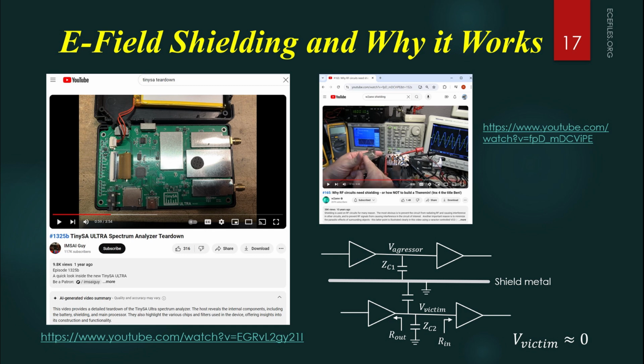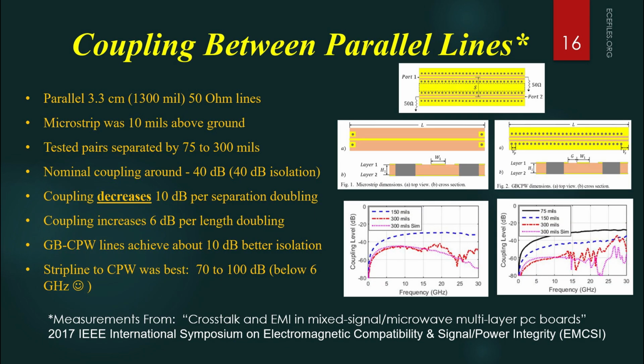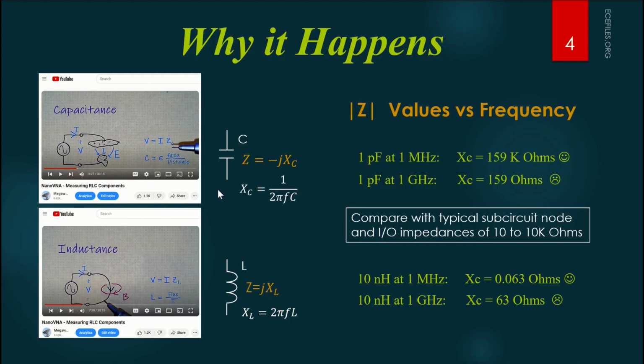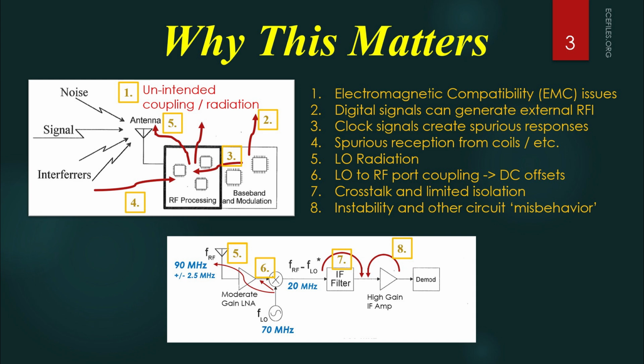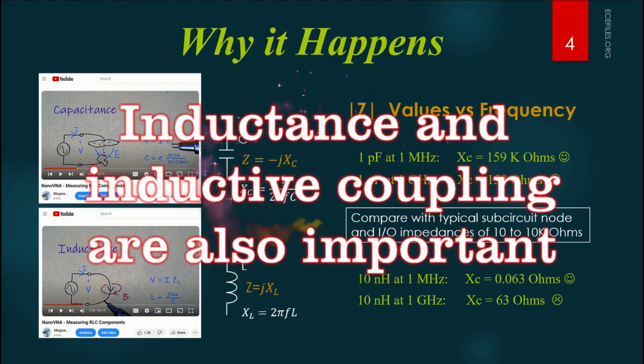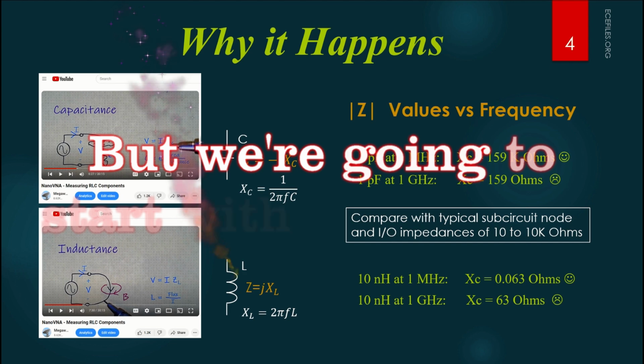And you may have heard of microstrip traces or coplanar waveguide. If you haven't, don't worry. We're going to talk about those and define those and why you need them. We build our circuits with transistors and integrated circuits and inductors and capacitors, but we also end up building things we don't think about, what are called parasitic couplings from one circuit to another. And to understand the effects of those on our radio frequency circuits, we model them as capacitance from one place to another. And it's not a capacitance in your circuit design, it's one that really comes from the layout or the construction of the circuit.